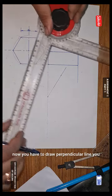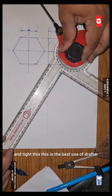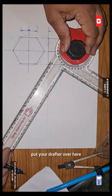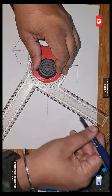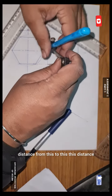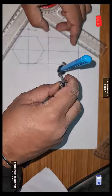Now you have to draw a perpendicular line. You need to fix your drafter over here and tighten this. This is the best use of the drafter. You just need to put your drafter over here and tighten it, and just draw a line, and you need to take the distance from this to this distance. You need to mark it over here like this.